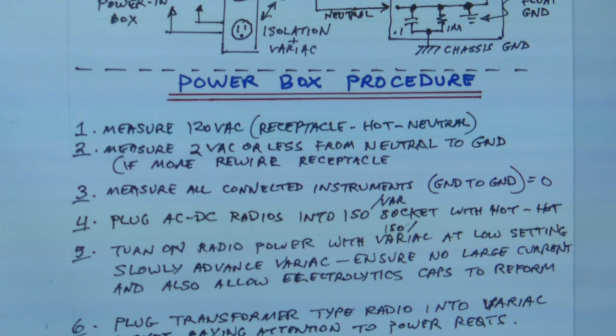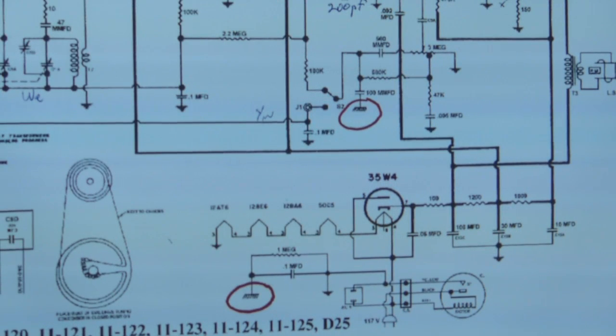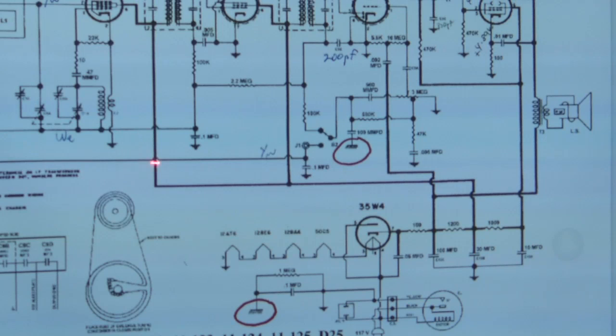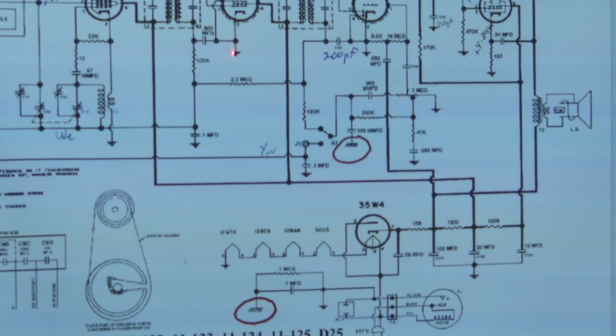Let me give you an example of that. Can you turn on the slide that shows the Crosley radio? Thank you. Okay, a typical 5 tube AC/DC radio, and you'll notice that all the little symbols for grounds are here, and those are all connected to the neutral, we hope, so that's the return path for the power. Here, here, here, all these little symbols here, but you'll notice there's a different symbol here and down here. Now those are the chassis grounds. So at that point, you don't have a floating ground, you have a chassis ground.